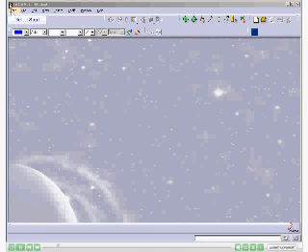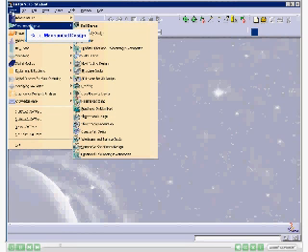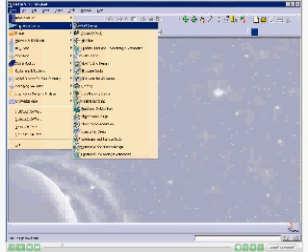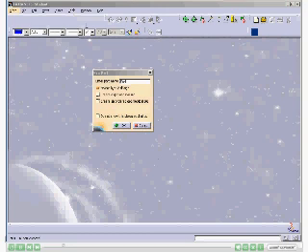Select Start from the menu bar. Now select Mechanical Design module. A contextual menu is displayed. Select the Part Design from it. The New Part dialog box is displayed. Enter C07-Tutorial in the Enter Part Name selection area.